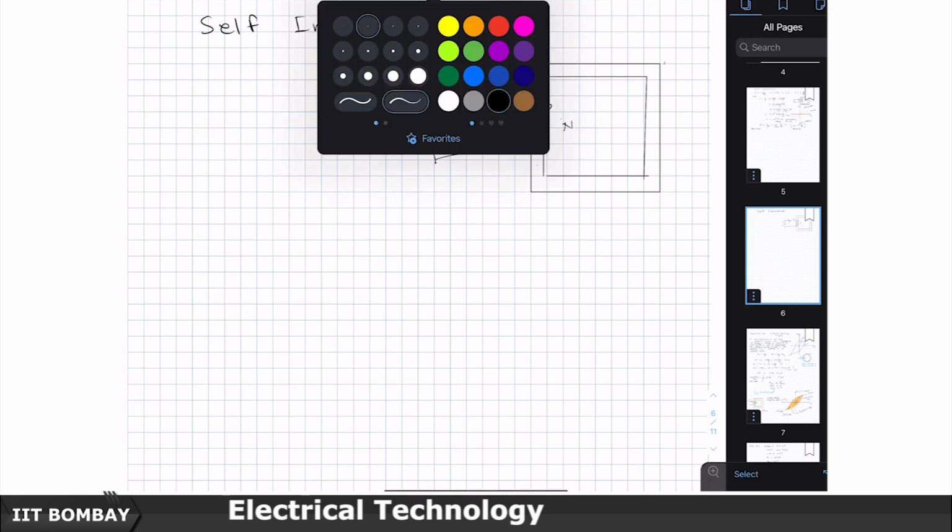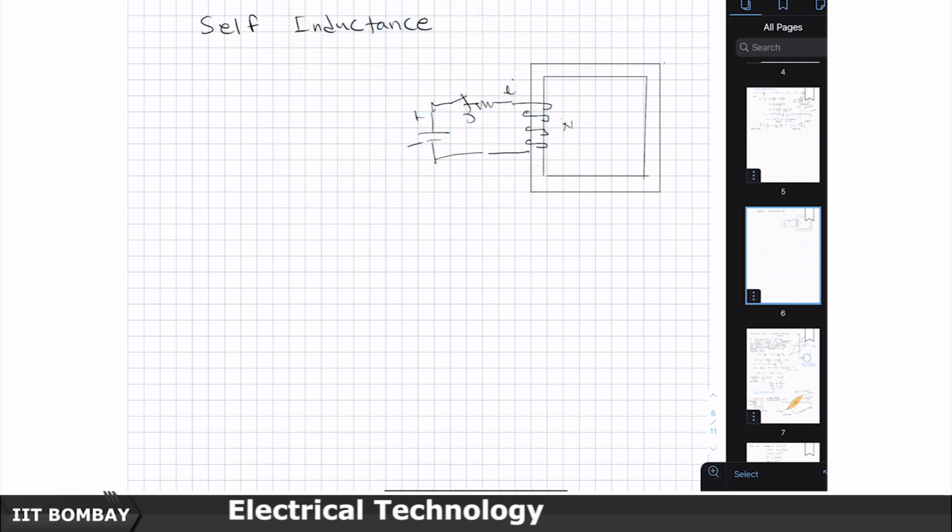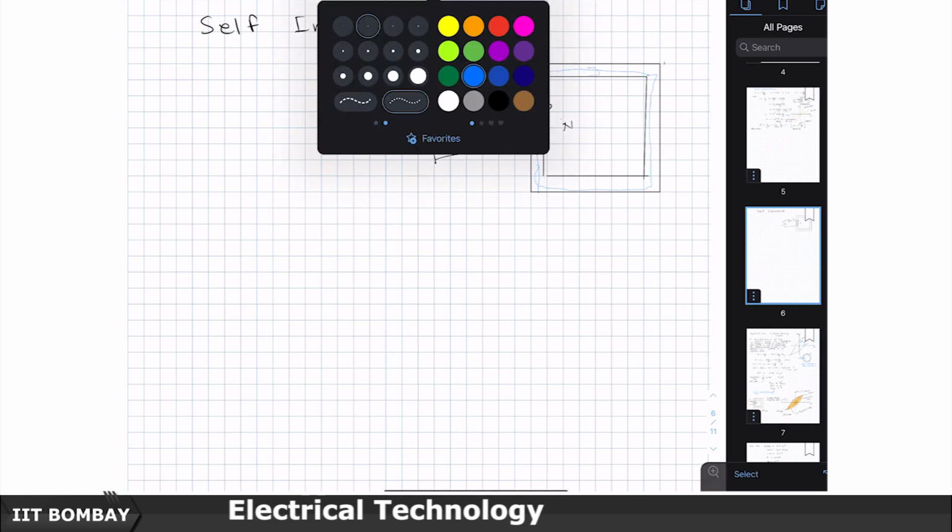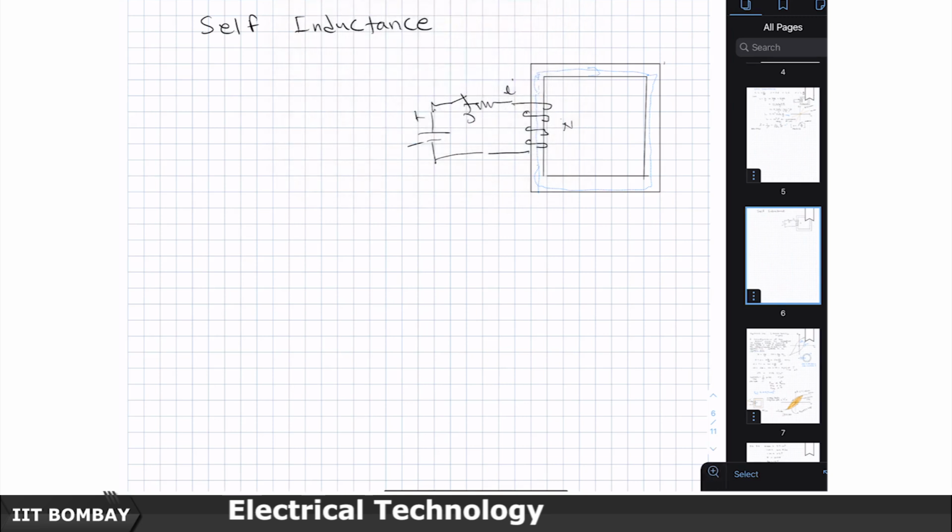So, again using the right handed screw rule, we know that this will set up flux lines which will follow a path like this, and then let us say that this has an area of cross section A in meter square, and now we know that this plus minus E, the way we have defined our convention of V and E. So, this will be plus d psi by dt, where psi is the flux linkage which is n times the phi.